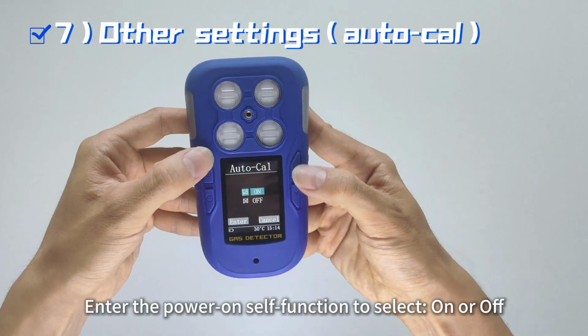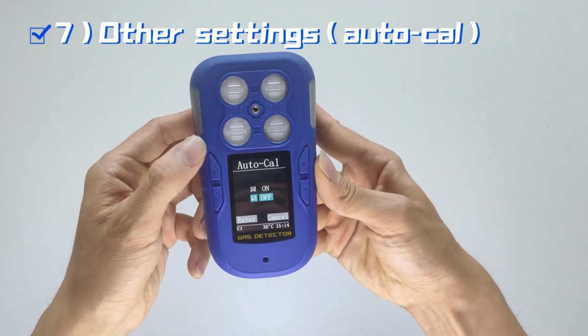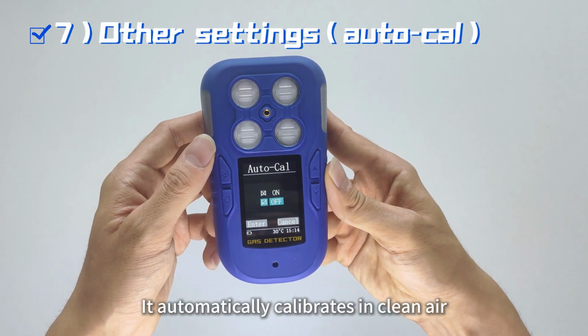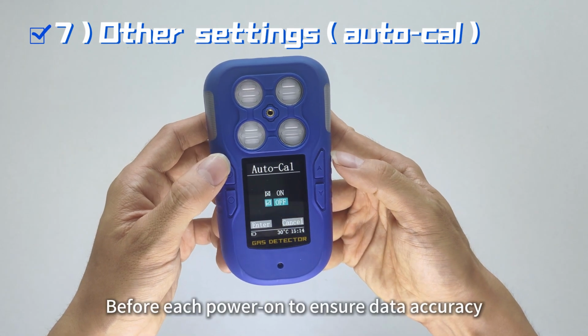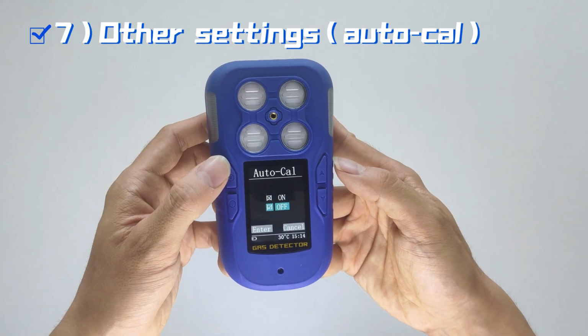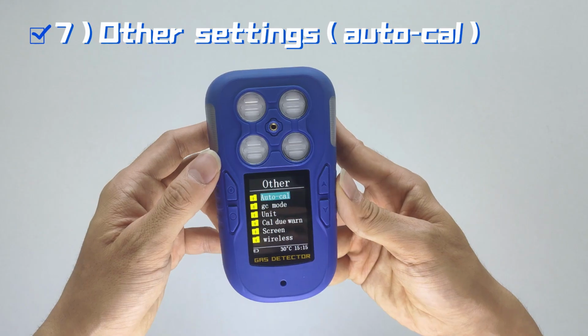Enter the power-on self-calibration function to select on or off. Generally speaking, we recommend enabling this function. It automatically calibrates in clean air before each power on to ensure data accuracy. The oxygen will be calibrated to 20.9% VOL.